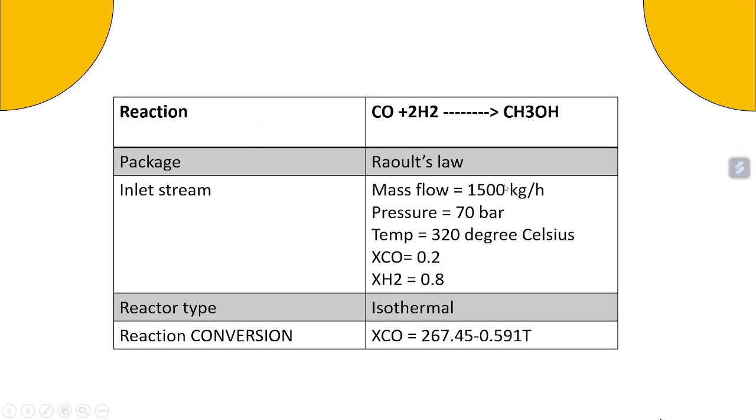Hello friends. So today we will be using DWSIM to simulate a conversion reactor. The reaction which we will be simulating is carbon monoxide reacting with hydrogen to give methanol. Both carbon monoxide and hydrogen are in gas form. The package which we will be using is Raoult's law.